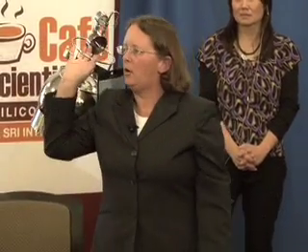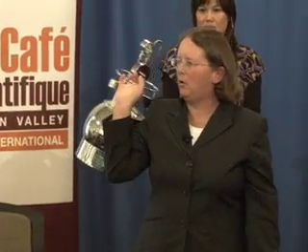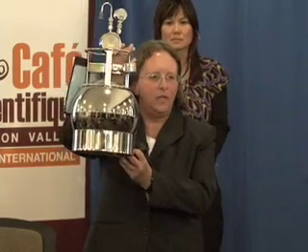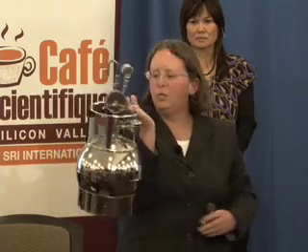This is our standard air sampling canister. This is a 6-liter Summa canister. Summa is a trade name, but it's basically a stainless steel evacuated canister. So this is hollow inside, and the reason that it's basketball shaped like this is that it's nicely polished on the inside. You want it to be spherical so that when the air sample is in there, it doesn't get trapped in the corners. If this were a square box, it wouldn't be nice and homogeneous. So this is a standard shape for Summa canisters.